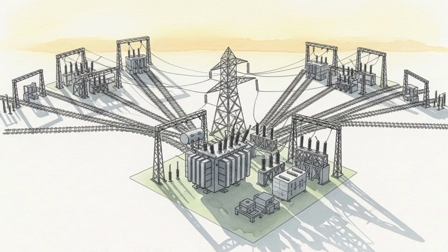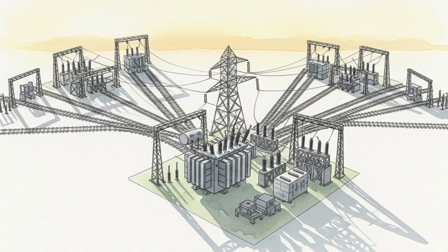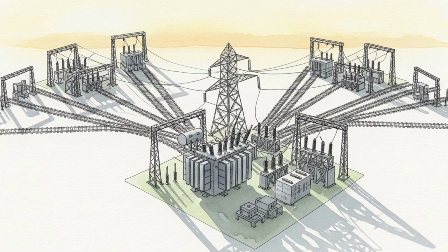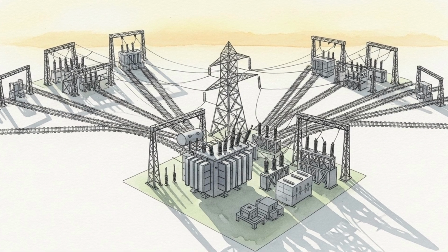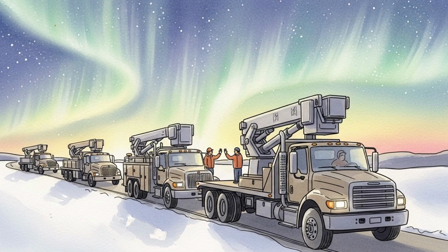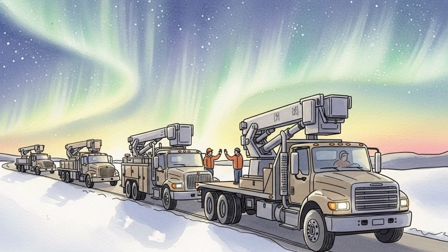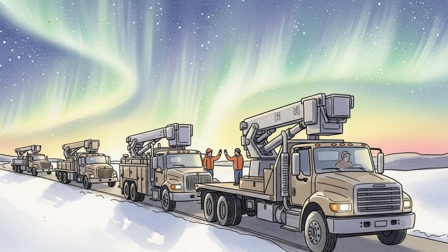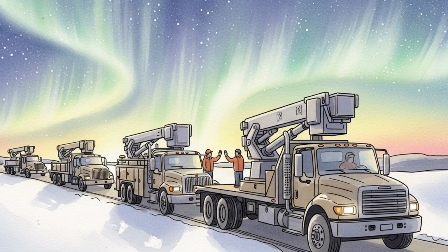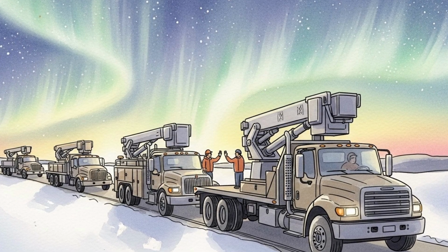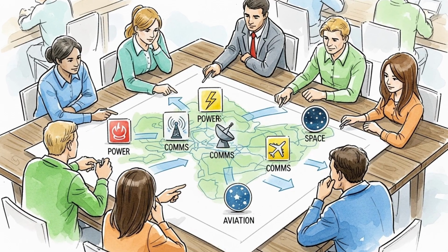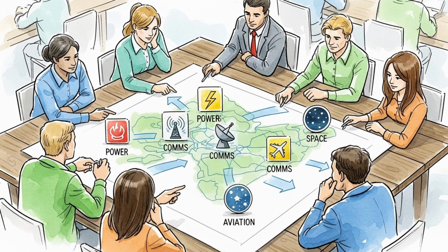In medium Earth orbit and geosynchronous orbit, drag is not the main driver. There, the primary risks are charging, radiation upsets, and station-keeping errors from disturbed sensors or reduced ground contact. Satellites in geosynchronous orbit maintain longitude and inclination with regular burns. Disturbances in sun sensors or star trackers can delay burns or degrade pointing. Payloads with tight pointing budgets, such as high-throughput communication beams or optical instruments, may suspend service until stability returns.